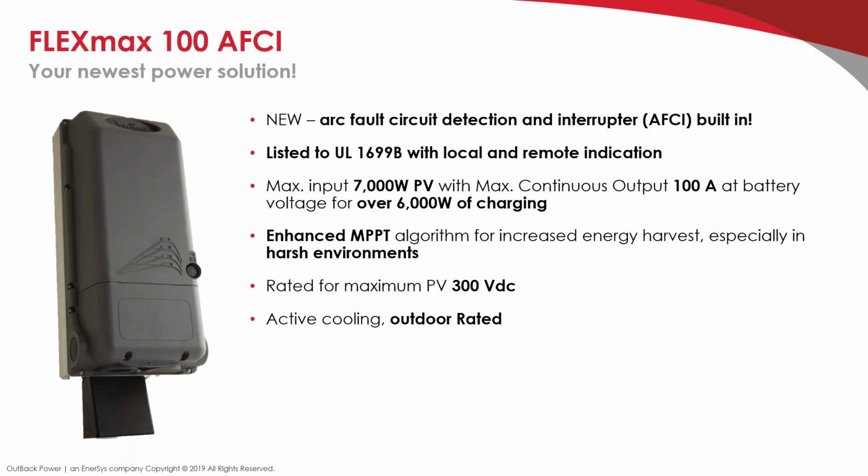And it has active cooling with a fan, and it's outdoor rated for NEMA 3R or IP56. Built-in ground fault protection as in the previous generation, and field upgradable firmware. So this firmware can be upgraded either through the gateway device or directly inside of the charge controller. Both options are available.